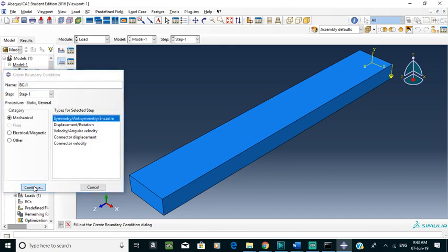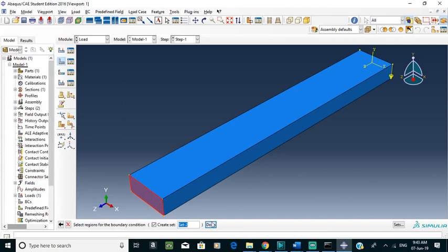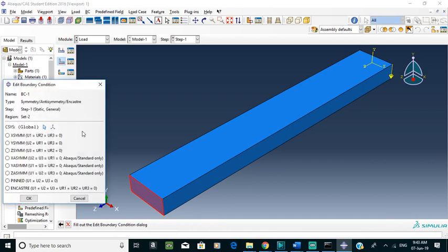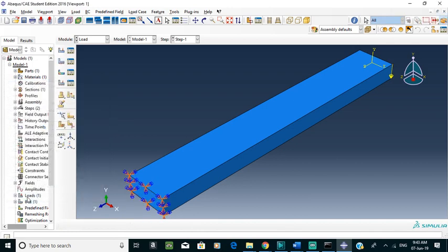And then you have your anchor, which is the section of your part which is actually stagnant. Perhaps it's connected to a wall, perhaps it's connected to another component, maybe by welding, by bolting. There's a lot of ways to anchor a component, but this is how we do it on the simulation. We select that anchor right there, and just like that, that's your anchor. Meaning this part is anchored, it is not moving, it's not supposed to move.